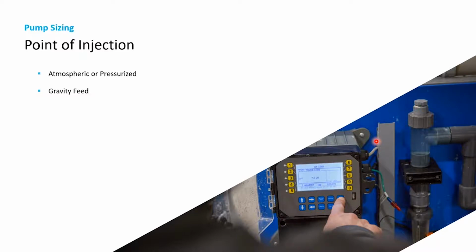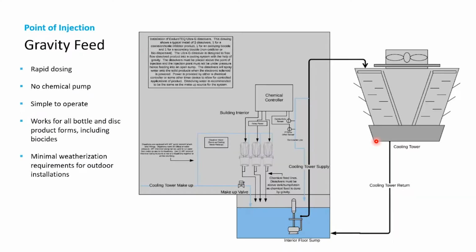The other style of feeding, and one that we have the capabilities of with our dissolvers, is the gravity feed. So with gravity feed, it's pretty neat. I mean, it's not a pump, but in my opinion, I think it's important to discuss here because it is another way of dosing chemistry. And if you have the capabilities of doing it, this is the one I completely recommend because it's simple, it's very economical, and it is very effective.